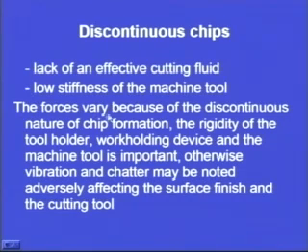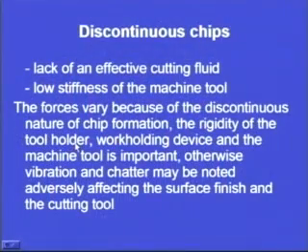The forces vary because of the discontinuous nature of the chip formation. When discontinuous chips are forming, the tool is not in direct contact with the workpiece all the time, so the forces may vary. The rigidity of the tool holder, the work holding device, and the machine tool is important. Otherwise vibration and chatter may be noted, adversely affecting the surface finish and the cutting tool.